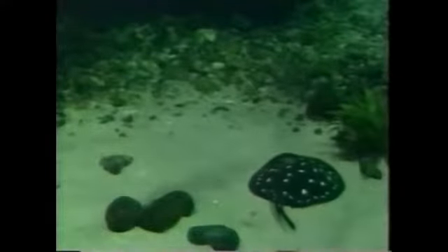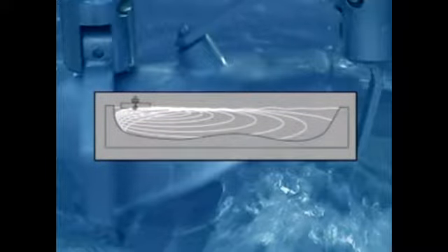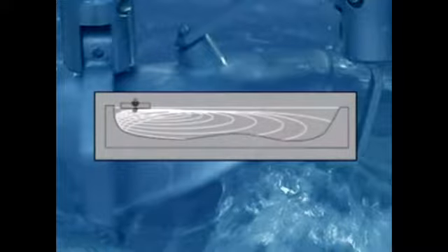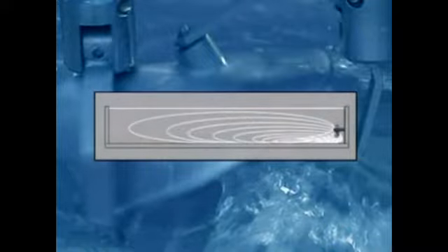The design of OLOID systems and their specially developed accessories permit a highly varied use. Its modular design allows it to be used installed on floats with a semi-immersed agitating body for aeration and agitation, installed on floats with a fully immersed agitating body for agitation without aeration, or completely immersed at a depth of up to 10 meters for agitation and circulation. All systems can easily be inserted into ponds, basins, and containers.